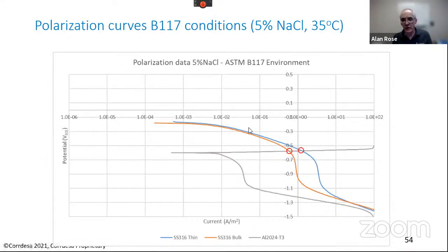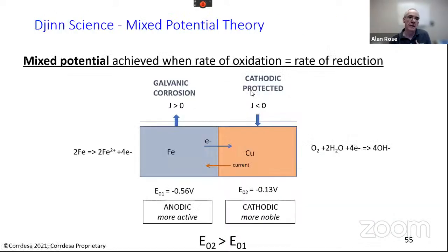And this is interesting because if you're familiar with these tests like the ASTM B117, it is a very intense, warm, intense 24/7 test. And it gives you no fidelity whatsoever. Components will corrode in there, fine, but they don't give you an indication of what they're going to actually look like when they're fielded. There's no fidelity. It doesn't know the difference whether it's a thin layer of electrolyte or a thick layer. It just corrodes the hell out of it.